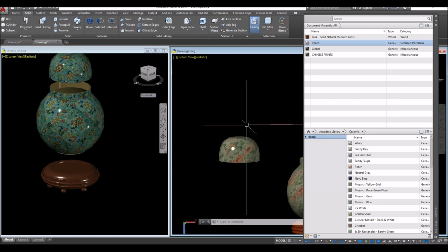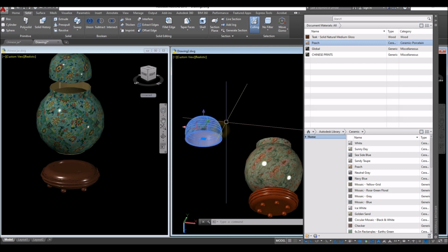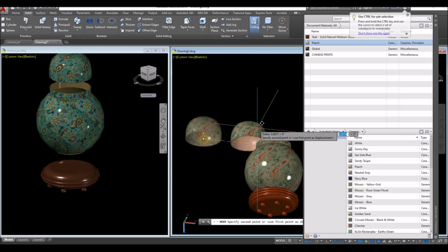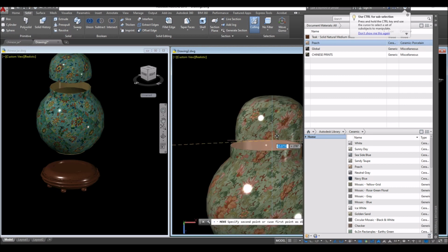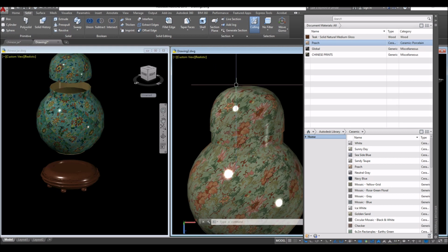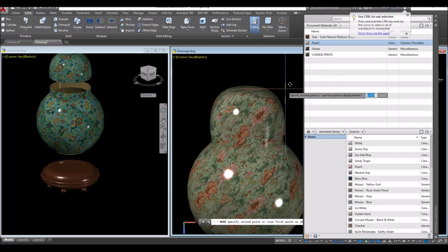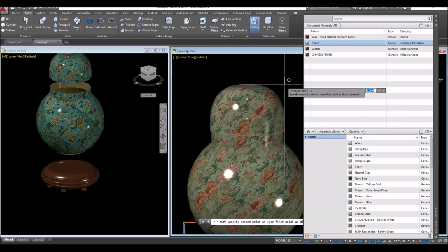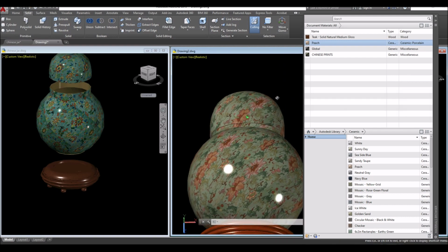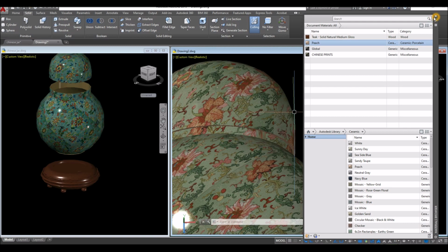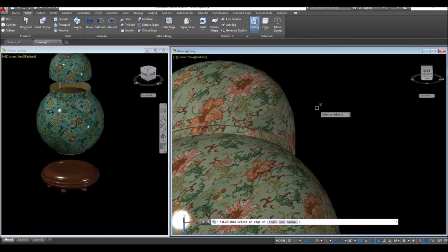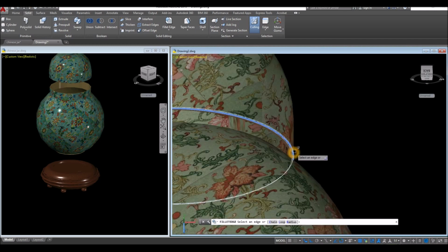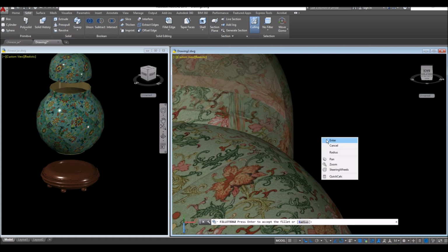Alright, so what I'm gonna do is move this one, move from the center and attach it to the very center of this, and maybe move this one a little bit downward. Turn on your ortho mode. So somewhere here, and maybe apply fillet edge, right click and select radius option and enter maybe 0.02. And just click this edge here. Just gonna smoothen the edges and enter.